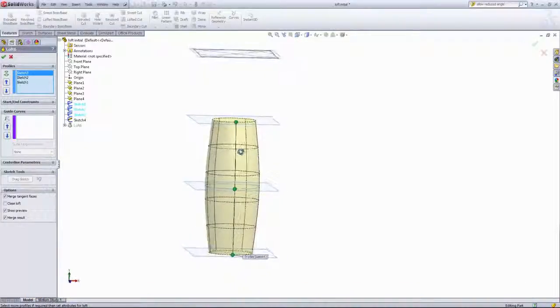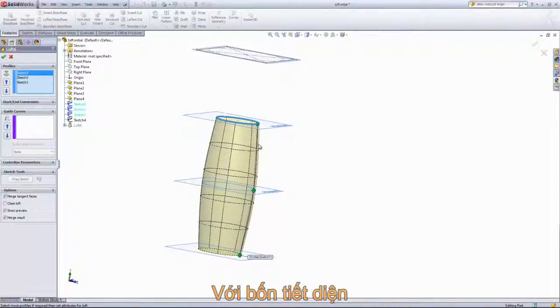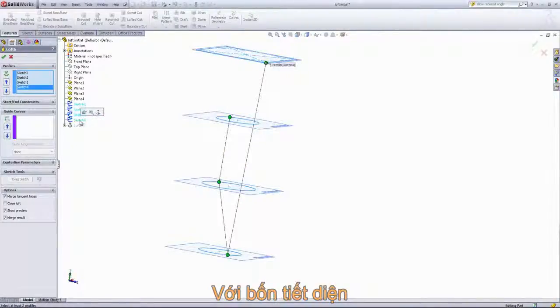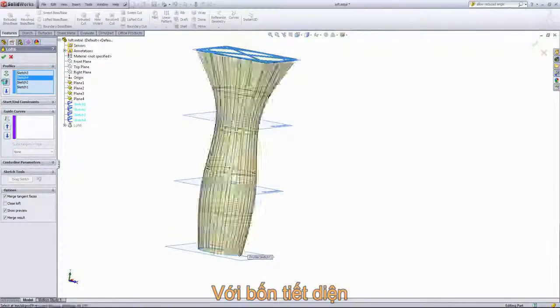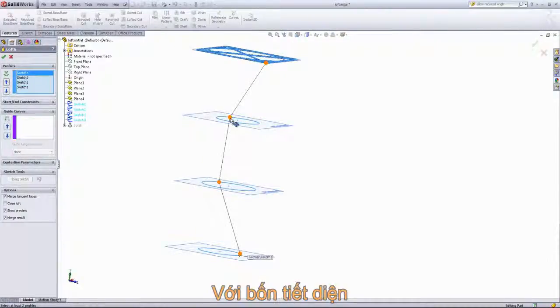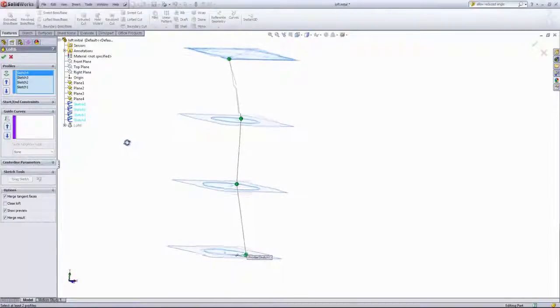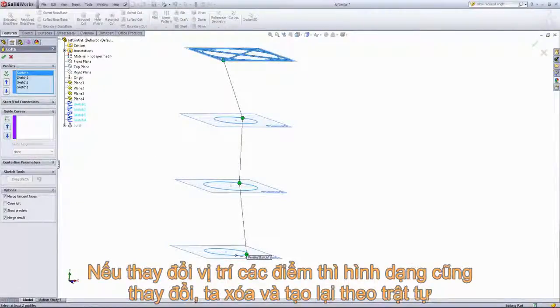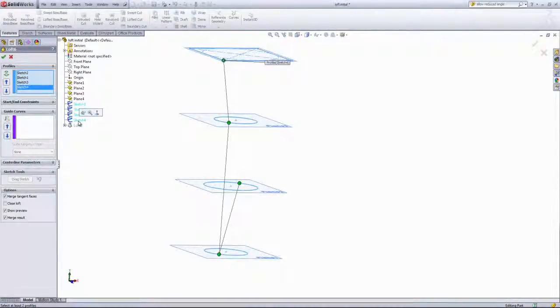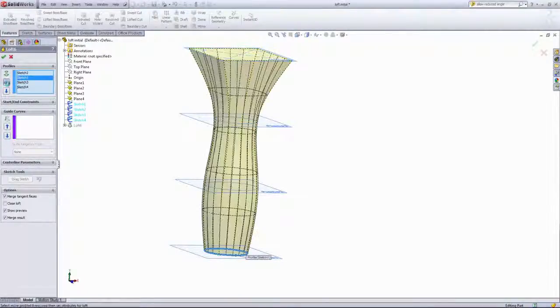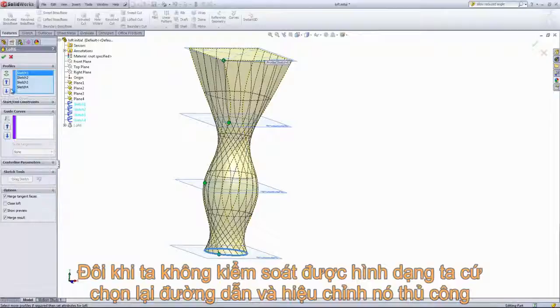as opposed to just straight lines. I'm not sure exactly what order or how the orders increase as you select more profiles, but with two profiles it would probably be a second order, and with the fourth profile I'm not sure if SOLIDWORKS takes it further beyond that. And once in a while when you select things out of order and try to reorder them, the connection points get a little messed up. So we can just come back in, delete these out, and just go in order. And that should connect the sketches.